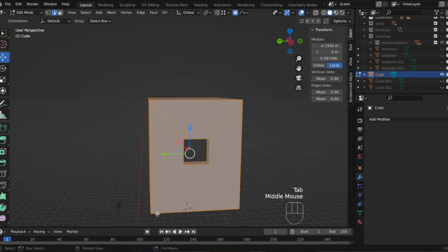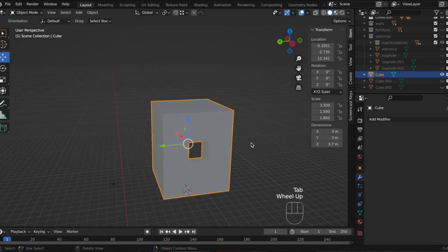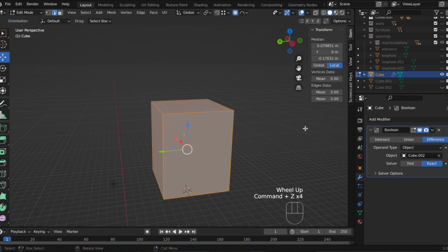However, we see that only two different faces have been created, and we don't need them because we need 4 square faces. So we can go back with Command Z and try the second attempt with the Inset tool.